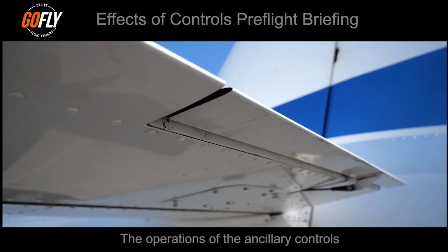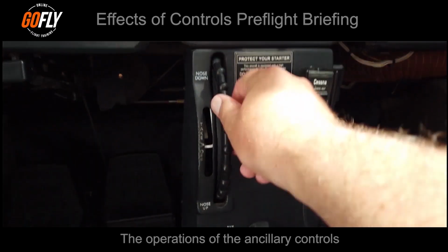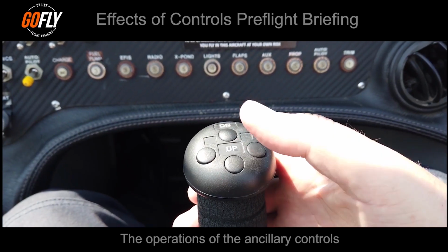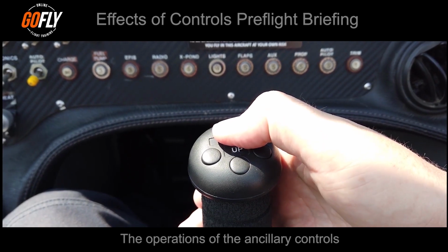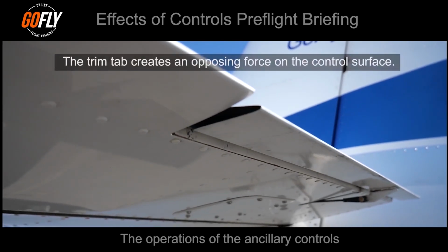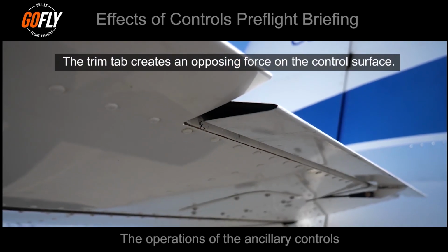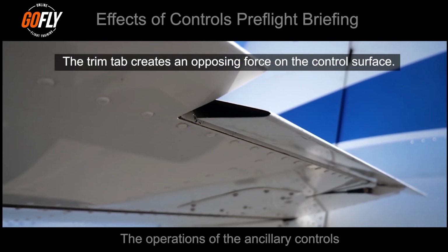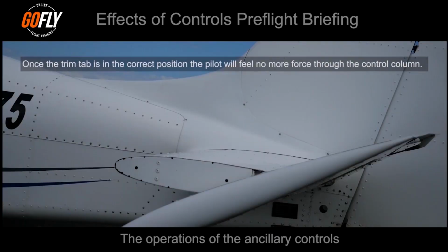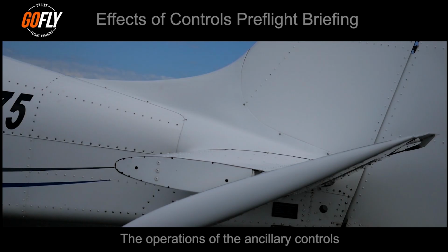The trim tab can be controlled in the cockpit with either a trim wheel or an electric trim button. The trim tab simply acts like a smaller wing at the rear of the elevator and creates a force opposing the elevator to keep the elevator in the required position for a particular maneuver. Once the trim tab is in the correct position, the elevator will stay in this position and the pilot will now not feel any force in relation to the elevator.